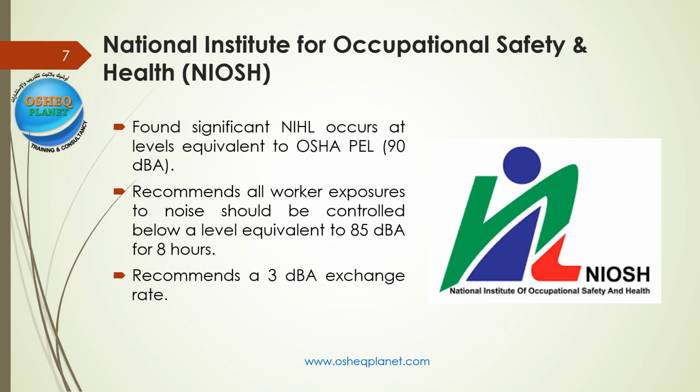It recommends all worker exposures to noise should be controlled below a level equivalent to 85 dBA for 8 hours. It recommends a 3 dB exchange rate. Decibel sound pressure levels are unweighted. dBA levels are A-weighted according to the weighting curves to approximate the way the human ear hears.